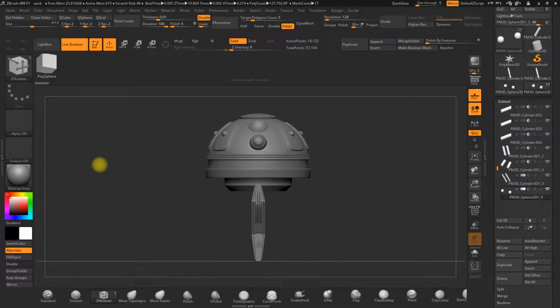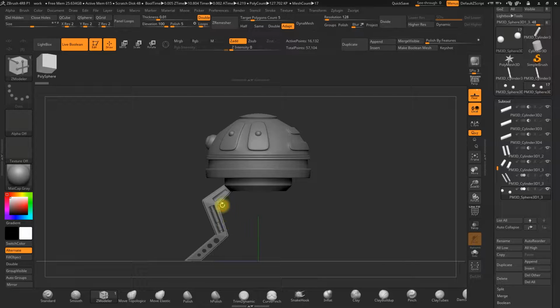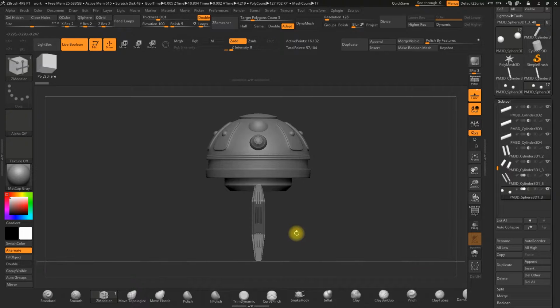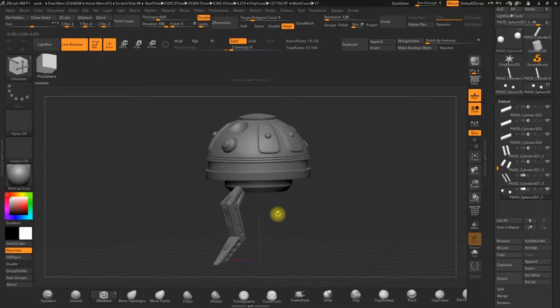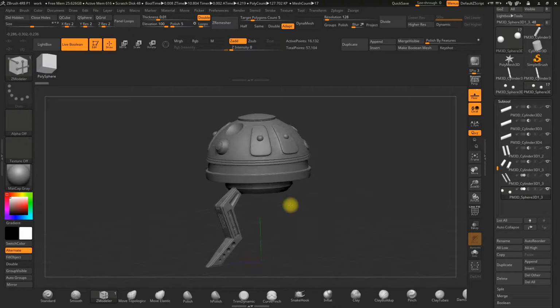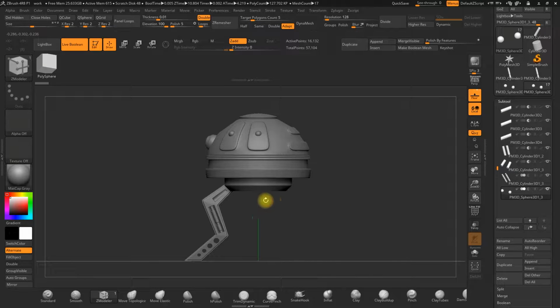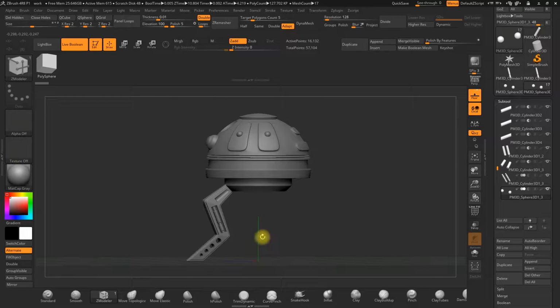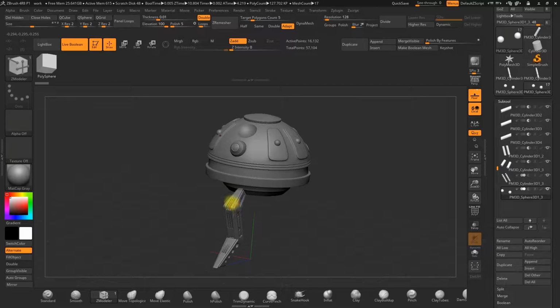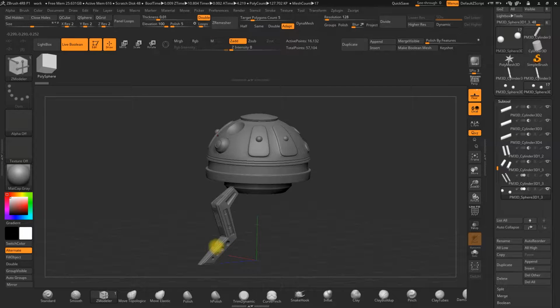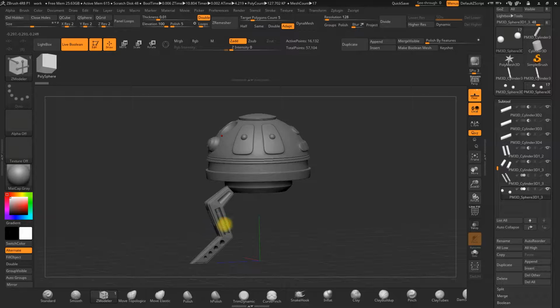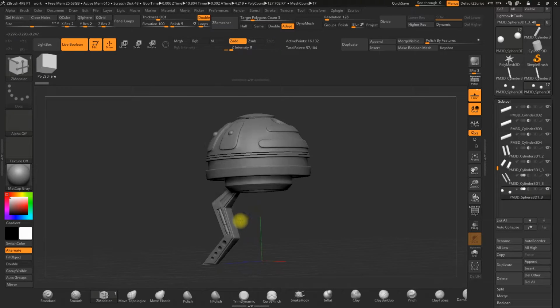Hello and welcome to the fourth lesson on this course, and what we're going to start to do here is join all these elements so that we can start to work on the leg and make various copies to work on the bottom part here. So to do that, the first thing we need to do is to join all the elements that make up the Boolean into one object. So all these tubes here, these elements, the holes, this part here, not the cylinder, okay?